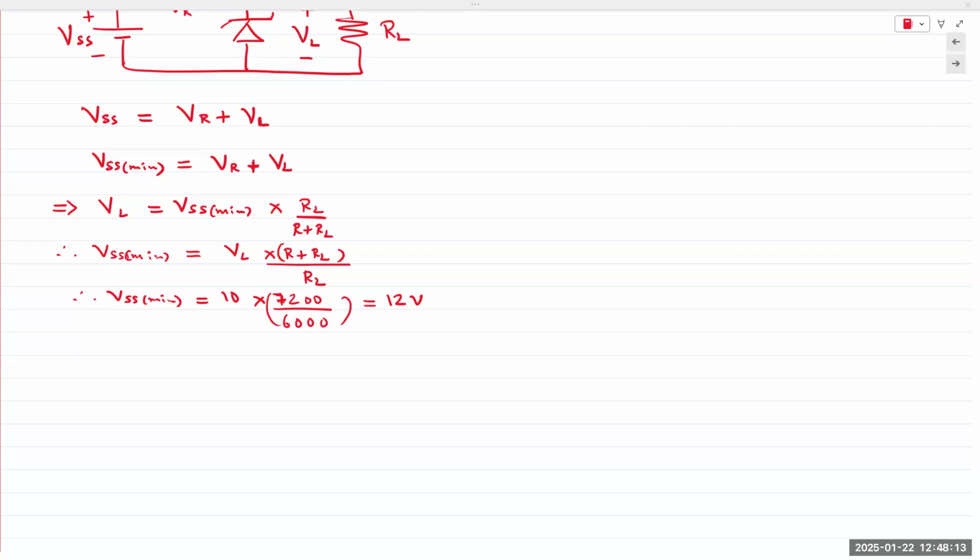If you want to find, so in this case, the design problem is what is the range of the supply voltage? Because that's a primary function of a Zener regulator: supply a constant voltage to the output, no matter what your input is. So the question would be, how much can your supply voltage fluctuate and still maintain the output voltage constant, right? So we'll have a maximum range that cannot be exceeded by the supply voltage, but there's also a minimum value, and the supply voltage cannot be lower than that minimum value. Otherwise, your Zener diode would not turn on.